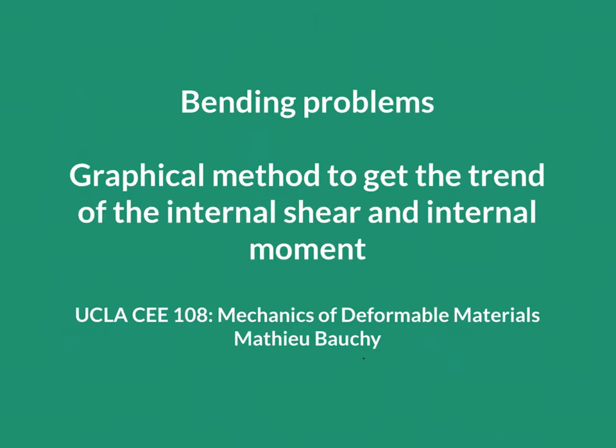So the idea of this graphical method is really that if you want to calculate the internal shear and the internal moment as a function of the position within a beam that is subjected to some transverse forces or some distributed loads, this is useful in order to calculate the normal stress and the shear stress that the beam is going to be subjected to.